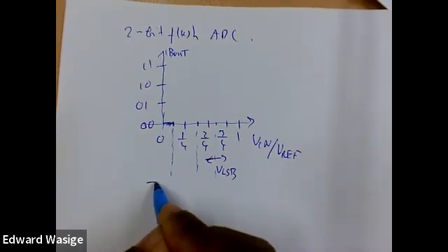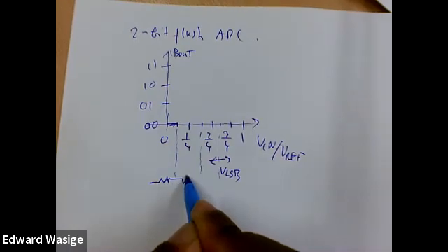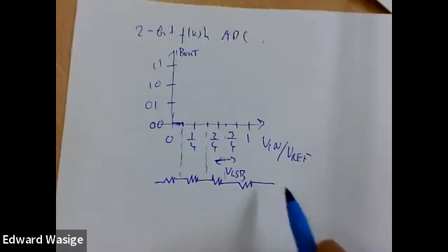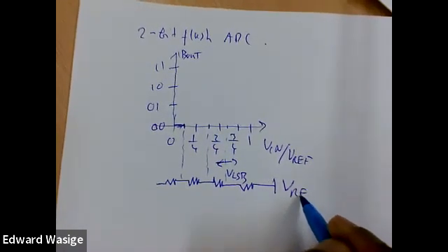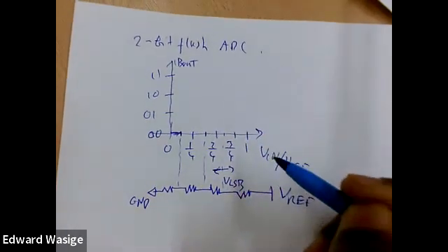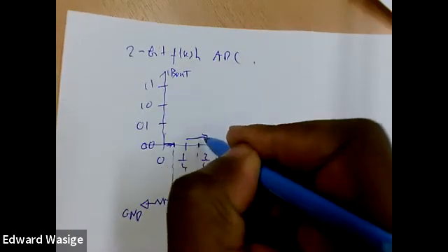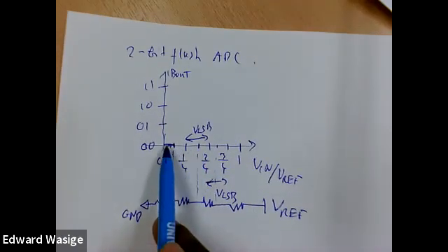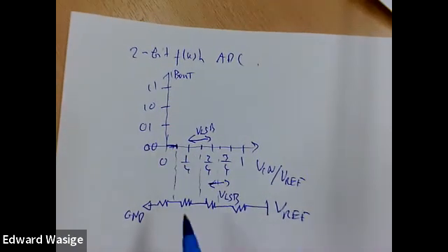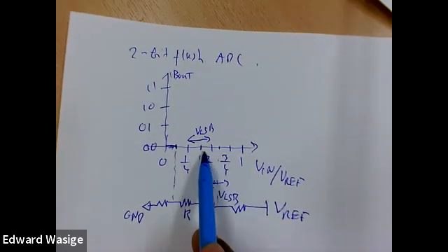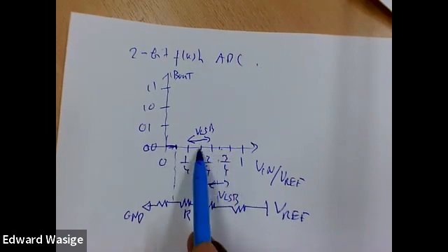So we'd like to generate, I can use a resistor chain to generate the reference voltages. So if this is my Vref, and that's my ground, remember the voltage between those two is VLSB, and between that point and that point it's VLSB. Here it's only half. So if I call my resistance there R, the voltage span between those 2 points is also VLSB, so that will be R.